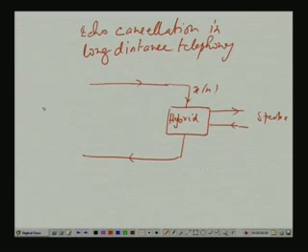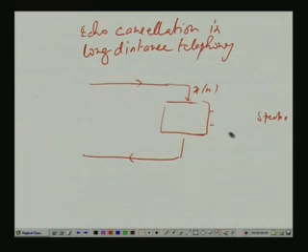To avoid that, we model the hybrid as a linear time invariant system, usually of very high order. Here you forget this for the time being, as though this is a filter h n, n from 0 to say L minus 1, a very large order filter, and the thing that comes out here is echo.